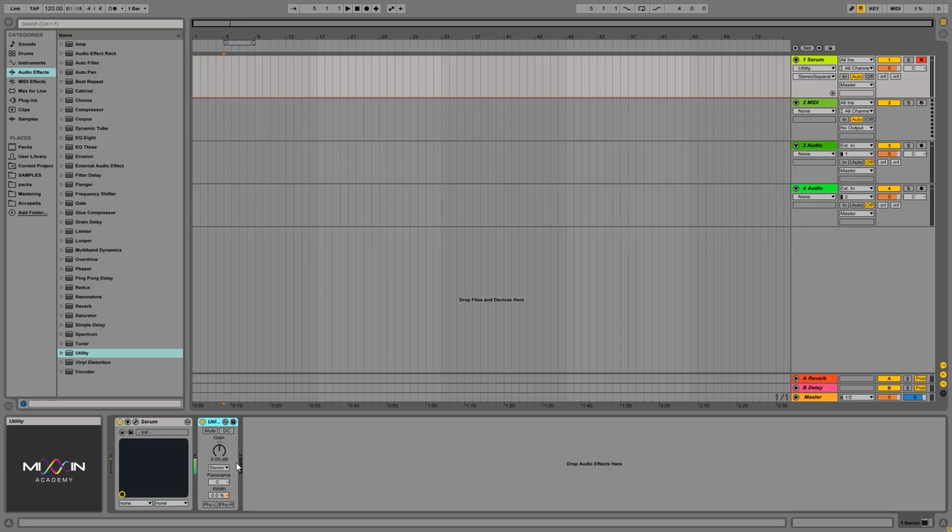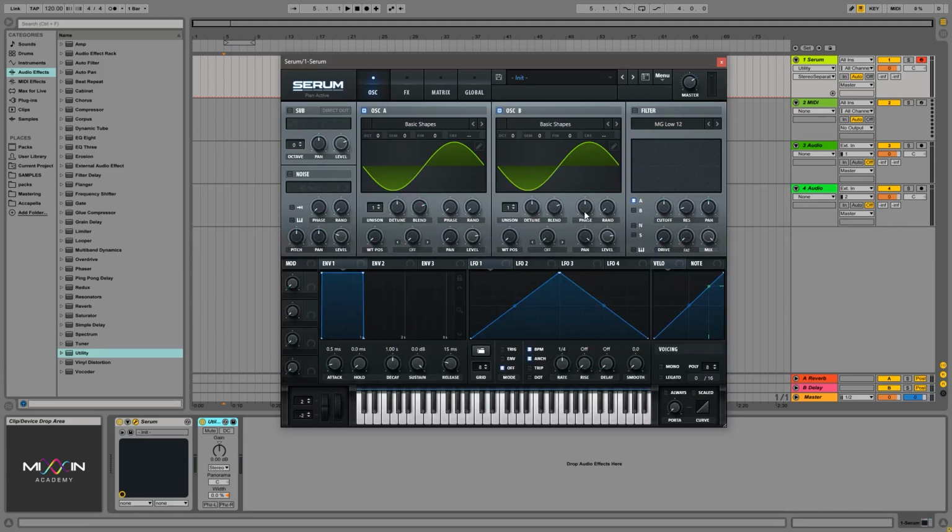So this is what would happen if you had a club that had a signal monoed out. So they had a monoed out system where both left and right play on both speakers. You would get no bass. So it doesn't mean that the bass has to be totally zeroed out like this. That would happen if the bass is completely stereo, so opposite phase, the most stereo it can be. Even if it was a little bit stereo, it would cancel itself out just a bit less. So let's do that. The more I change this phase, the less is going to be zeroed out.